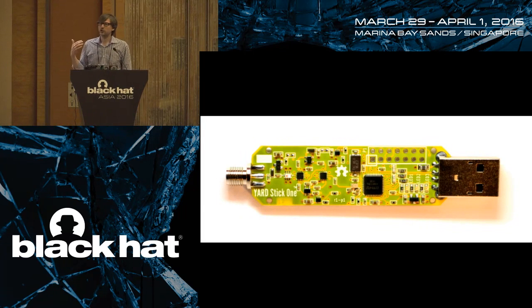And it implements certain modulations. It implements amplitude shift keying and frequency shift keying, which is like digital AM and digital FM. It implements on-off keying, which is just turning on and off the radio, basically a crude AM. And it has a very flexible packet format. So it's compatible with a lot of different wireless ICs, not just things from the CC1100 family. And that's why I chose it for Yardstick 1, is that it's one of the more flexible parts in this category of wireless transceiver ICs. So we can configure its modem to talk to a wide variety of different low-speed digital communication systems.